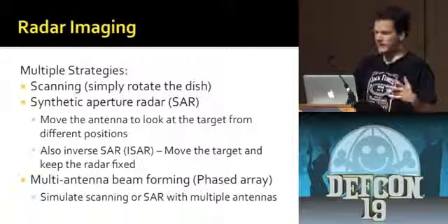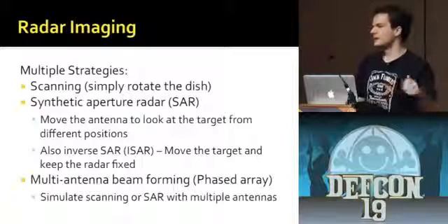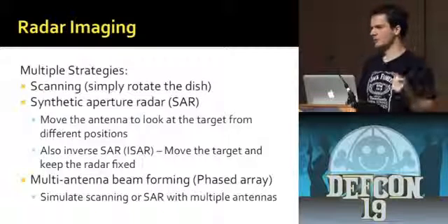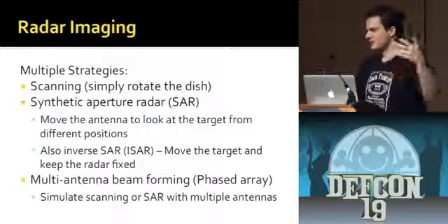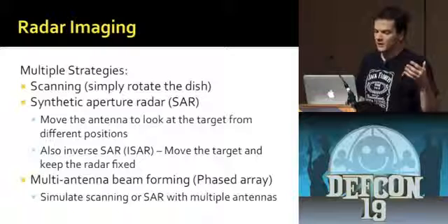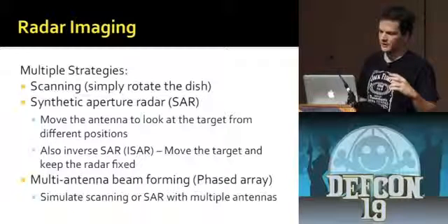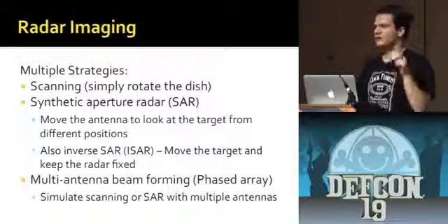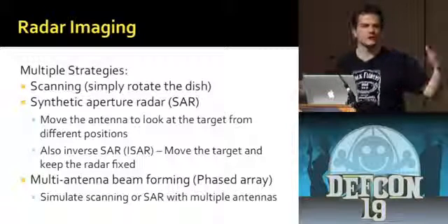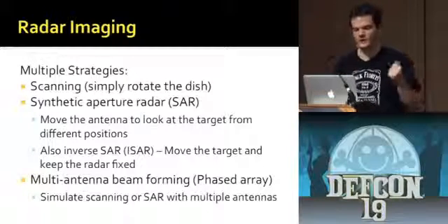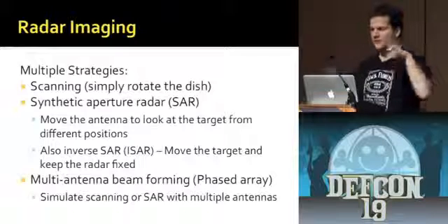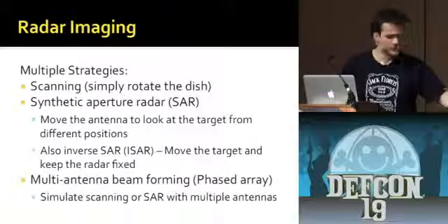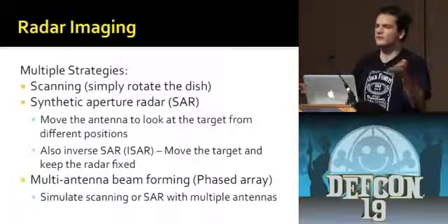There's something called Synthetic Aperture Radar, which basically means you can get better resolution if you have a bigger dish. But the problem is the bigger dishes are more directional, so that's the advantage. With synthetic aperture radar, you're actually taking coherent measurements of the signal at different places, and you're trying to simulate having a larger dish. The reason you would do that is so that you can get a finer resolution of space. If you just point it in one direction, the beam widths on these things are like 40 degrees or something, so you couldn't see anything out there.